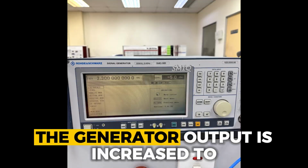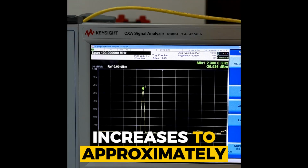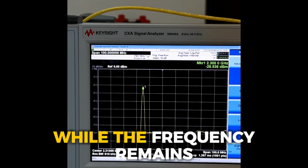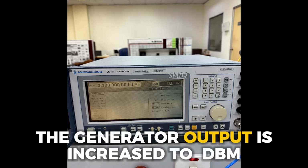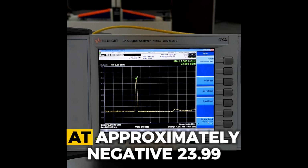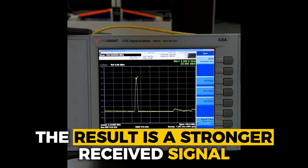Next, the generator output is increased to -5 dBm. The received signal strength increases to approximately -26.54 dBm, while the frequency remains unchanged. And finally, the generator output is increased to 10 dBm. The received signal is measured at approximately -23.99 dBm. As expected, increasing the transmitted power results in a stronger received signal.